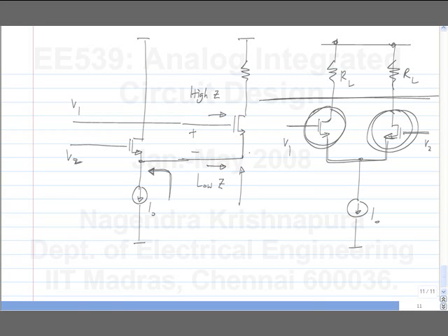So the important thing is to come up with some topology that will do your job, right? After that, analysis is very simple. If you know Kirchhoff's current law and voltage law, you will be able to do the analysis. So we'll continue with that tomorrow. But this is sort of the workhorse of the feedback amplifier, right? So you have an amplifier with two inputs, and both inputs look symmetrical, and this is universal enough that it's used in practically every feedback amplifier that we know of. Any questions?